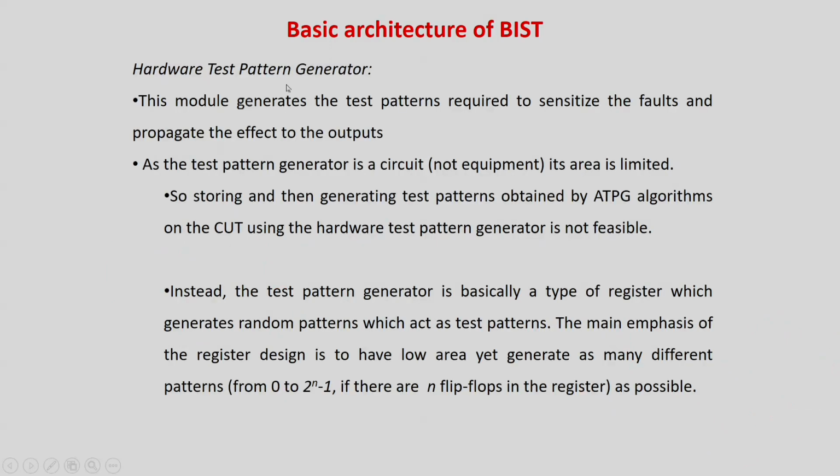That is not possible. So what is the hardware test pattern generator? It will have a state register of n bits. But as the test pattern generator is a circuit, not an equipment, its area is limited, as I already told you. So storing and then generating the test patterns obtained by the ATPG algorithm on the card using the hardware test pattern generator is not feasible. Therefore it cannot be a predefined counter. Instead, the test pattern generator is a type of register which generates random patterns, so the pattern sequence is not something I am controlling.